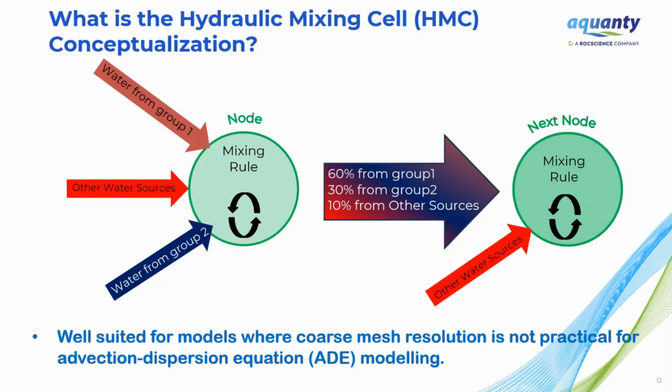And so those water sources, I'll show examples, but you could tag precipitation, you could tag overland flow, you could tag ponded water in the model domain, you can tag pre-existing groundwater, and you can basically apply a tracking zone anywhere in the model that you're interested in.